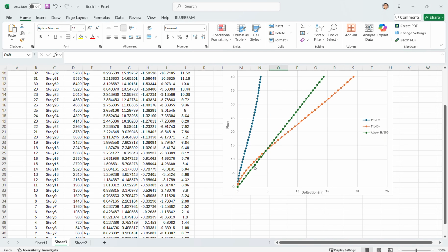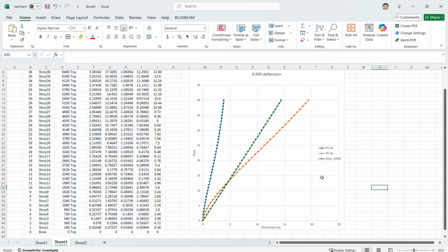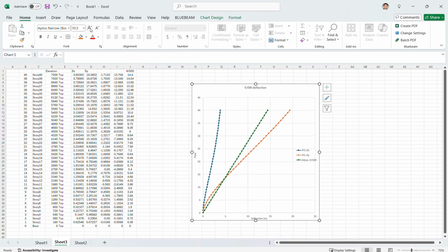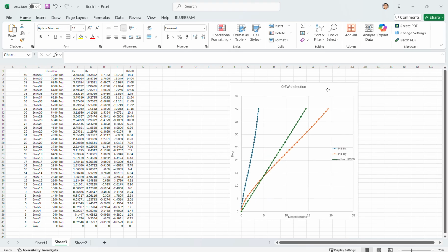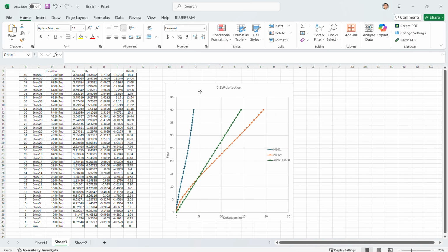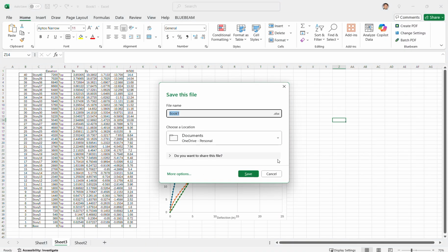So in the current model, we have some issue in Y direction, right? So this is model 1. I think maybe make it a little bigger. So we need to iterate a few more times so that we increase the lateral stiffness. So I'm going to stop this at the first, and then we're going to move on to the second round.